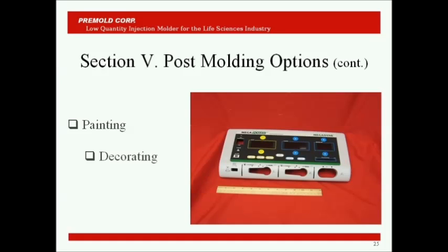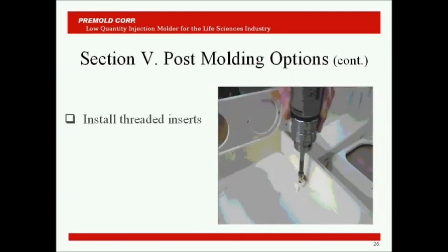If threaded inserts are desired for your application, you can use a self-tapping style of insert shown here, put in by either an air or electric-powered driver. Usually the hole is molded in the plastic part, so it's molded to the correct size, and then the insert is put in just like a self-tapping screw, but it's a one-time installation. So having that threaded insert in there, you can run your screw in and out as many times as you want to assemble and disassemble the product.